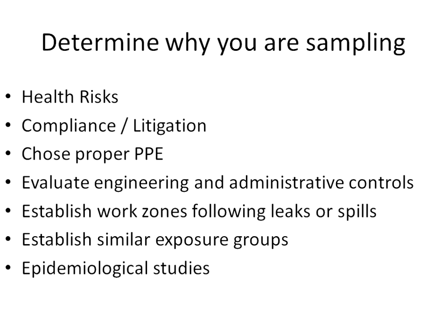So maybe the loudest noise when you do your noise mapping is closer to a piece of operating equipment, such as a large fan or generator, and that is double hearing protection. But when you step back a certain number of feet or yards, you're in a different zone and you can remove the muffs, and then hopefully coming into the work area can have a completely different zone.